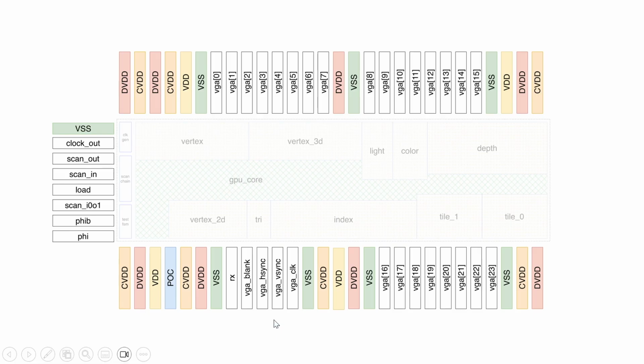After about 1 month finishing the placement for the DUT and other system modules, we started working on the IO pads. There are some strategies we did and we would like to share. The first is actually decided in the previous APR stage that we sacrifice one side of the IO pads for more area. We can see that we only have 3 sides of IO pads here. Apart from the input and output signal pads we needed, the power pads required are the dirty VDD, DVDD, and the clean VDD, CVDD here for pad power supply, the VDD for chip core power supply, the VSS pad for ground, and the POC pads for pad enablement.